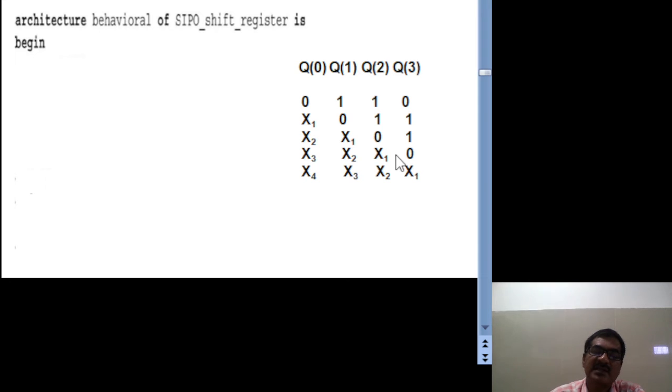Like that the data will be entered into the register by 1 bit for each clock pulse, but you can extract all the bits from the register at a time, since the Q is declared in the form of a vector. Okay, so therefore the output always shows the 4 flip-flops value of the register.